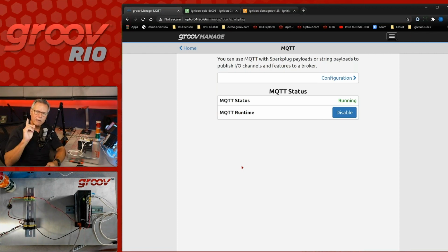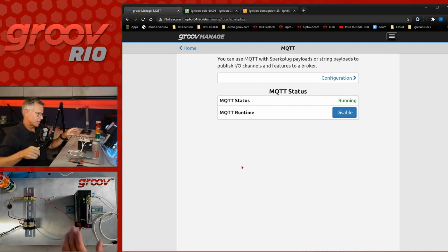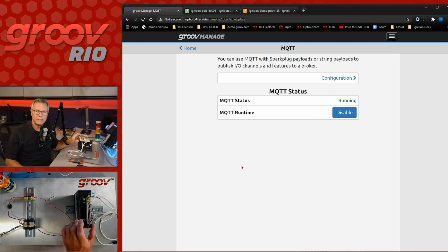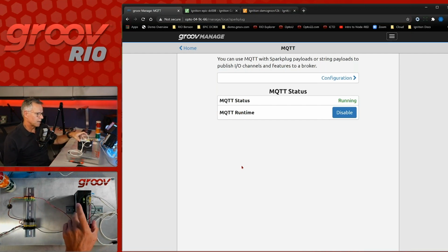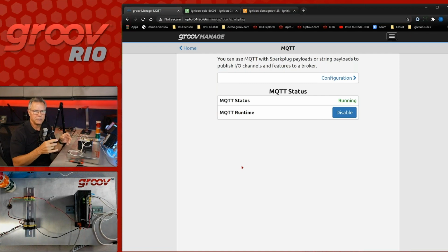Sweet. Okay, and I saw another question come up, and I want to make a point of this. This is rather important. One of the questions we get a lot is: what kind of IT involvement do I need to allow Doug from Pennsylvania to actually write to an output here? The answer is zero. When I got on the network with my Groov Rio and got a DHCP address, that means I also got a gateway. If the network is properly configured, you're going to have a gateway to the internet, and that's the same as your PC. You get an IP address, you get a gateway, so you can go to google.com.